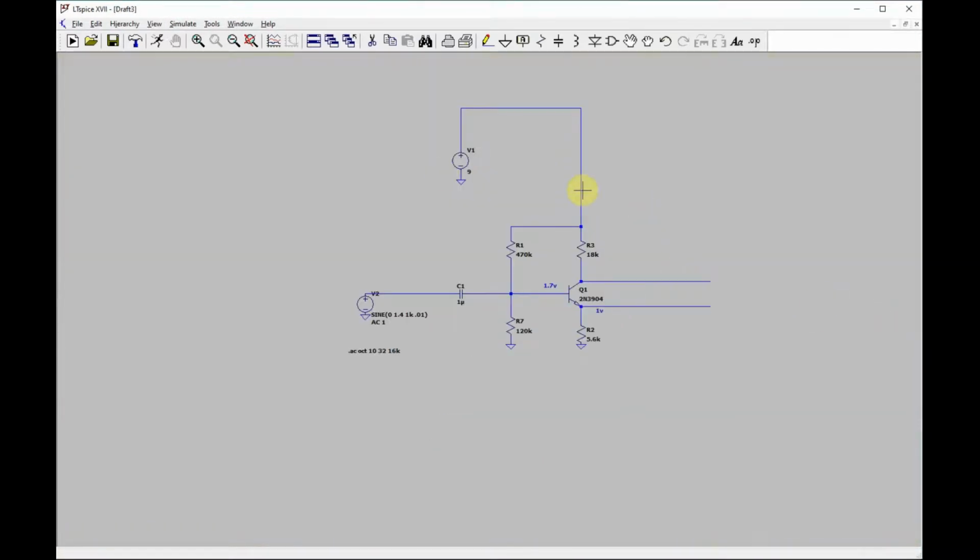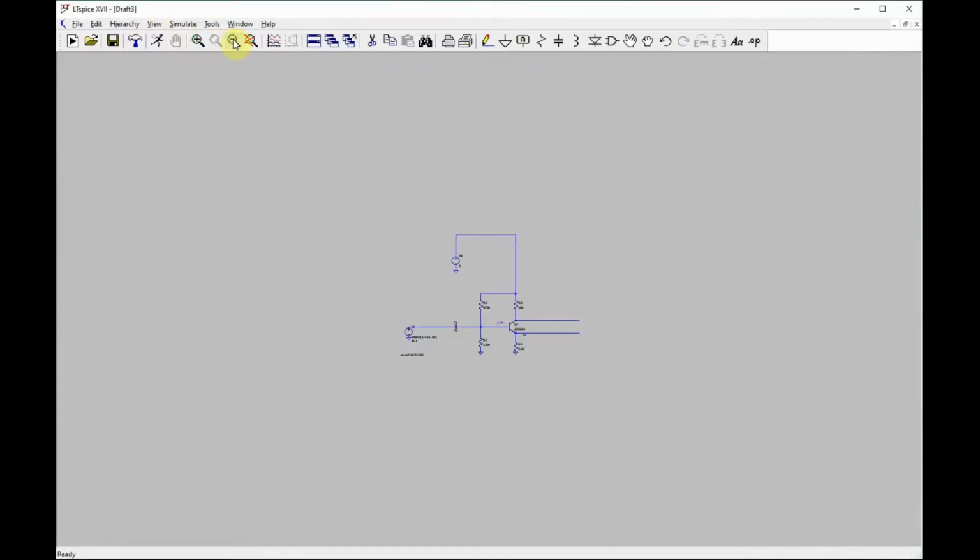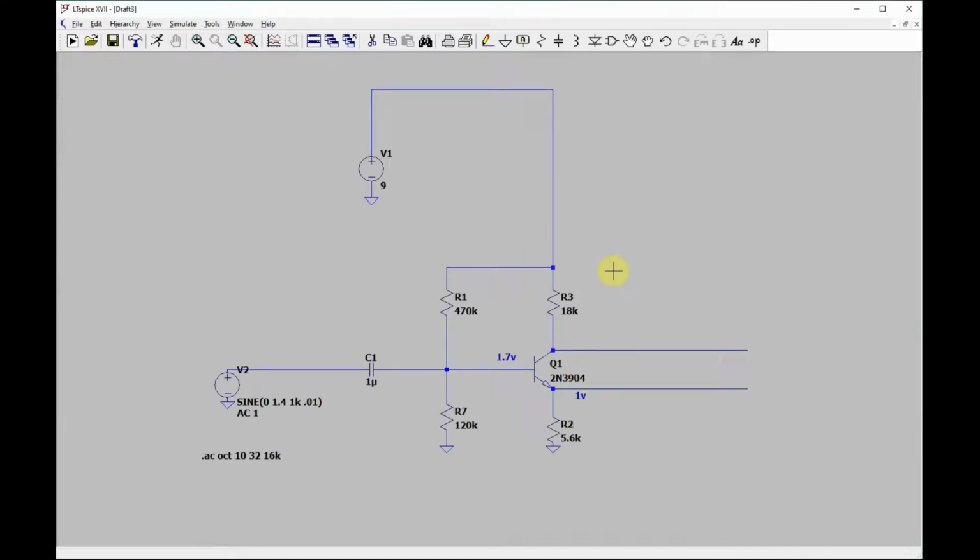But anyhow, so this is basically how I usually build them. Now, that's the standard part, right? This is just a way you build a Class A amplifier. Now, there are two tricks after this that I use all the time. And the first trick is going to be a bypass capacitor. And here's how I usually do it. These two tricks, they're just indispensable to me.